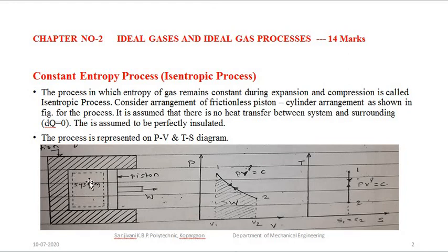We call it a system, and we enclose this system with a perfect insulation, shown by the hatching lines. So a perfect insulation, a piston cylinder mechanism, and 1 kg of ideal gas we have considered here. The dq or q, that is the heat transfer between system and surrounding, is considered as 0 here. Then and only then will we achieve this condition, the constant entropy process.